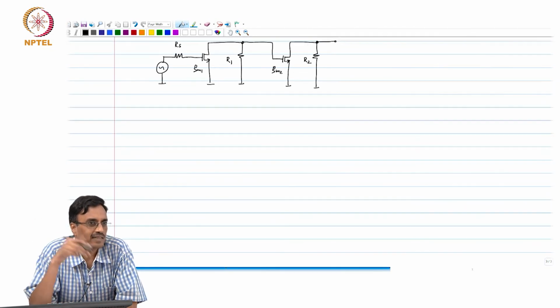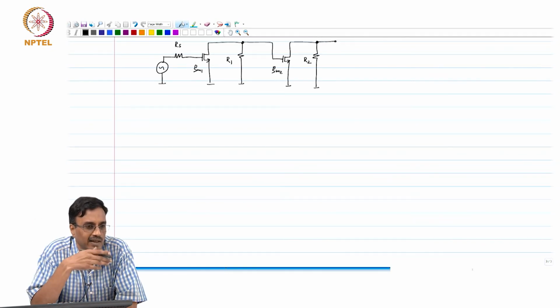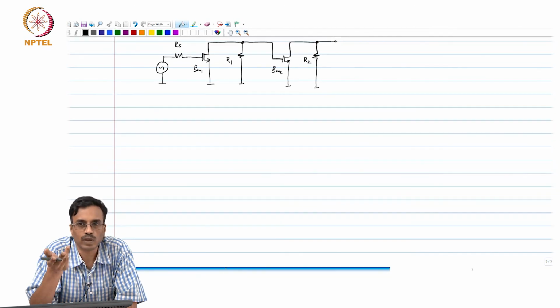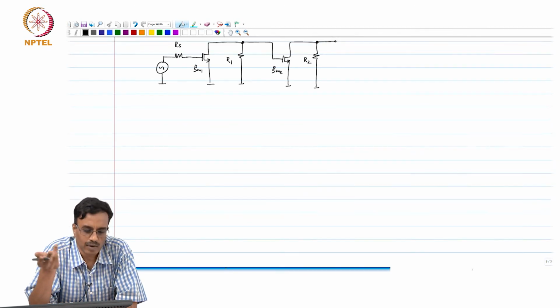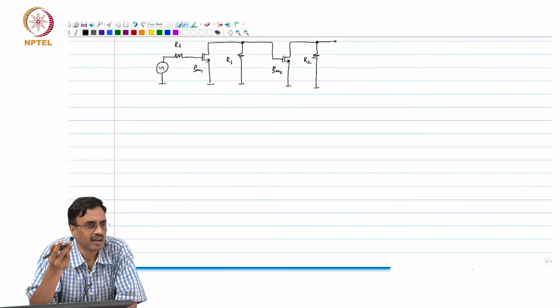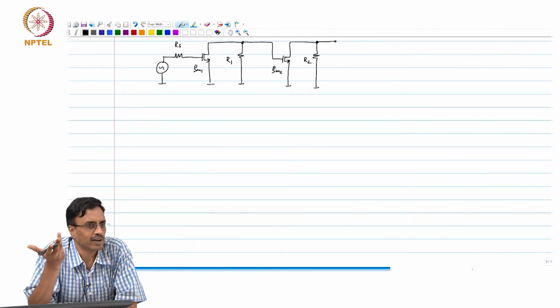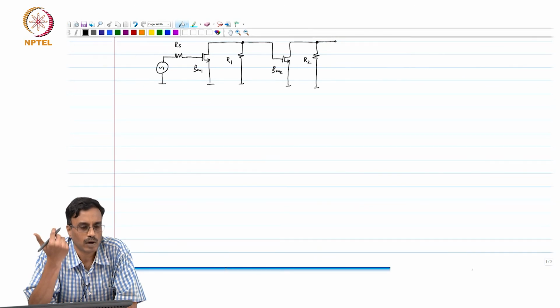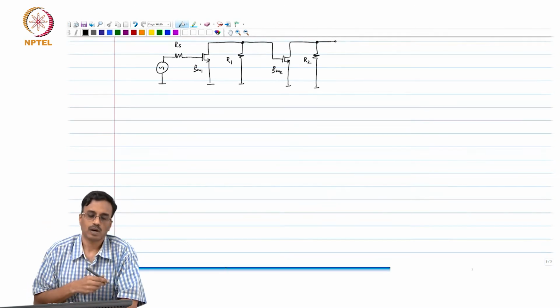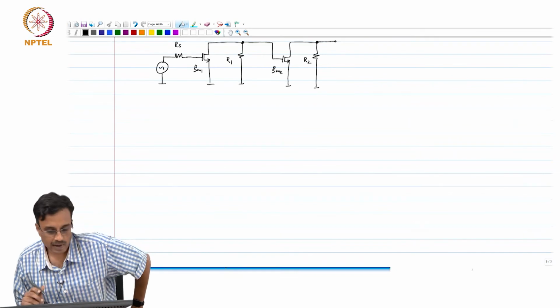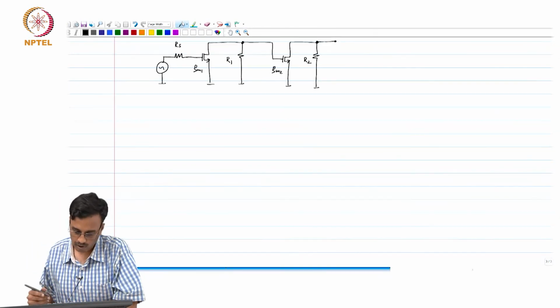So basically, wherever you see a gain, you replace it with a transfer function, and therefore in general noise factor is a function of frequency, because gain is a function of frequency, all right. So that basically is all I had to say about noise factor.